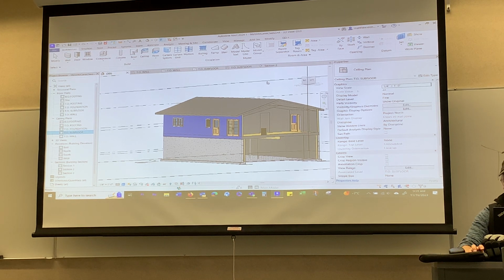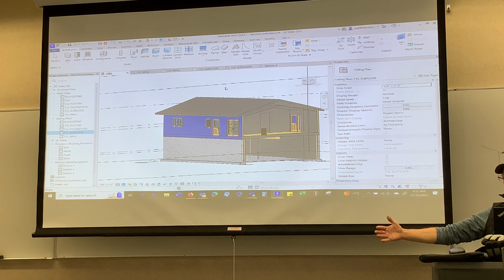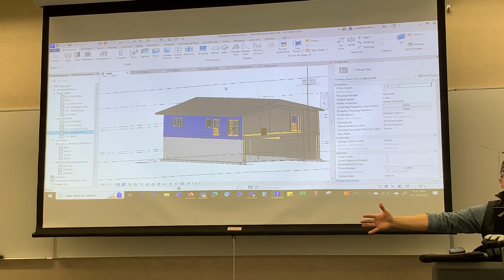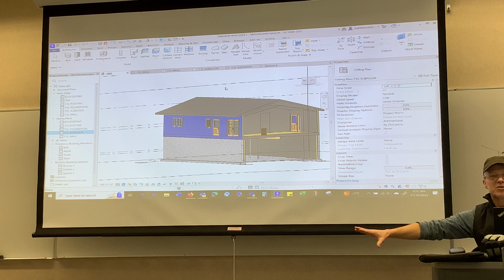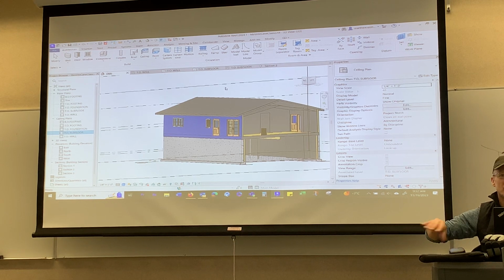And there's all kinds of code around stairs, because people fall downstairs, so there's a ton of code with stairs, right? Landing size, door placement, handrail placement, rise and run on the stairs, width of stairs, all that stuff, there's a ton of it. Even where you put the doors and stuff, you actually have to allow room at the bottom of a set of stairs for people to fall down the stairs. You can't put a door at the bottom of a set of stairs, it has to be, I think it's 4 feet, or 3.5 feet. You gotta give a landing spot for when someone falls down the stairs. Because if they fall down and hit the door, they get hurt worse, or whatever. Yeah, oh yeah, it's pretty gnarly. And it's pretty easy to build stuff wrong. Okay, quote of the day. It's easy to build it wrong.